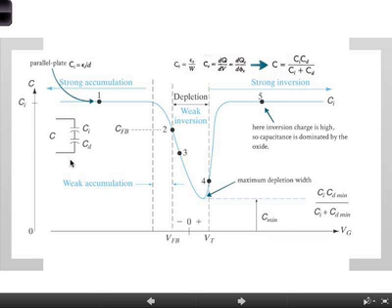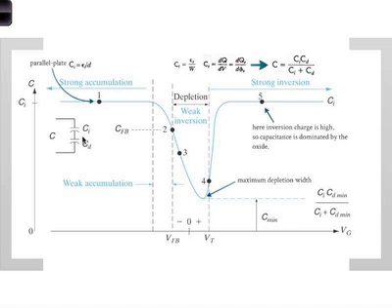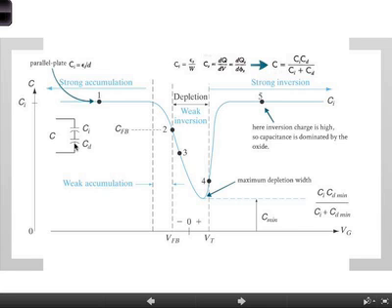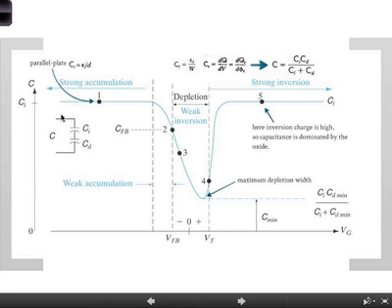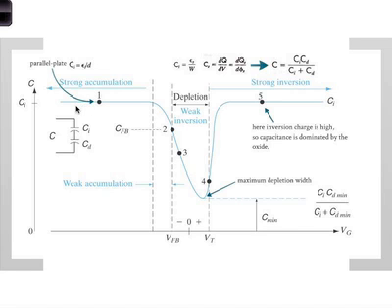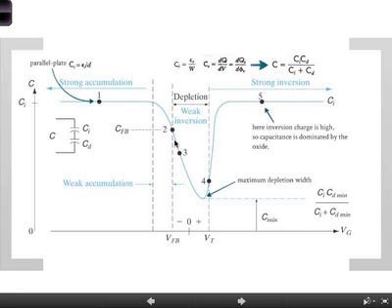So the model of the capacitance is very simple. You have a CI in series with CD. Now CI is not voltage dependent. It's fixed. Okay? It's just like an oxide, right? It's just the thickness of the oxide that determines that capacitance. In series with CD, which is voltage dependent, which depends on the depletion region and any majority carrier contribution. When you have strong accumulation, it's almost like a metal. Sorry. So it has no extra capacitance in the semiconductor, so just the CI. As you start getting depletion, this capacitance goes down to some minimum value and then goes up again as you get strong inversion. So keep that picture in mind.